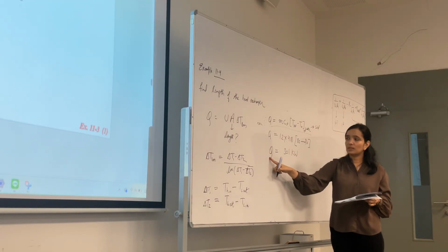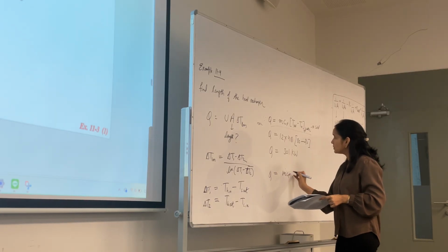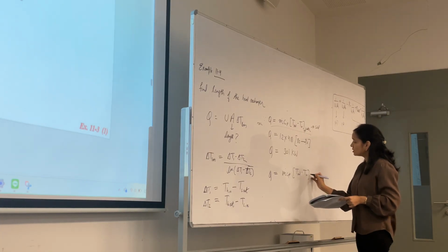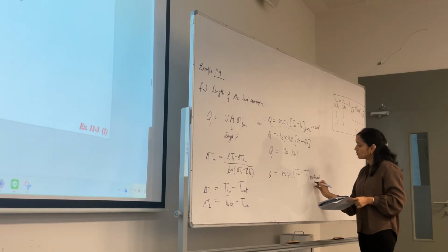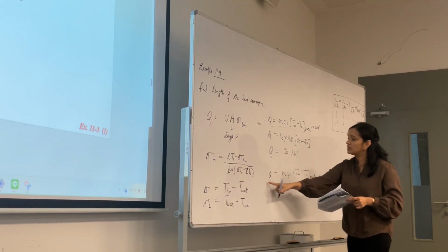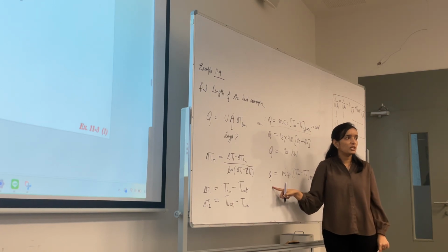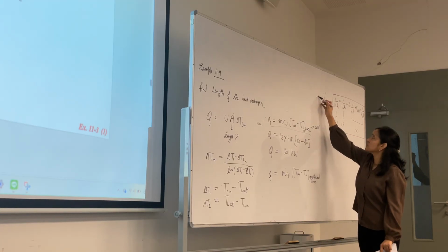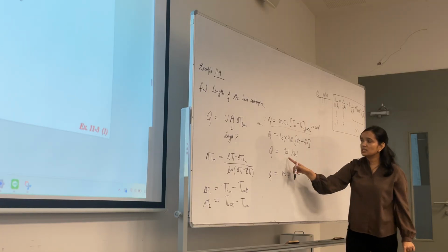Just like chapter 3, your heat transfer rate stays the same. This is steady state, right? We can use the same Q for m Cp, T in minus T out for the geothermal water. This value stays the same because it's steady state. In chapter 3 we had glass windows, you remember? The Q there was the same, and just like that, this is going to be the same here.